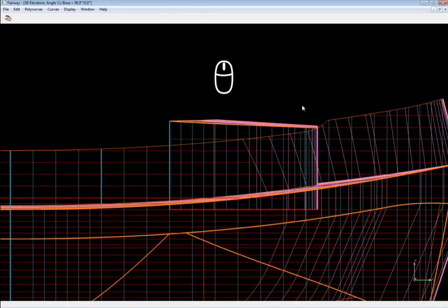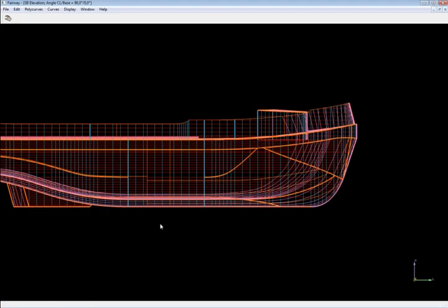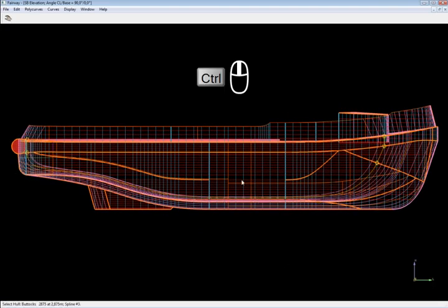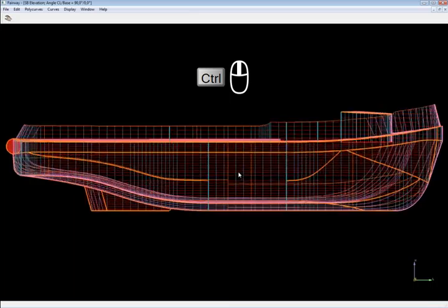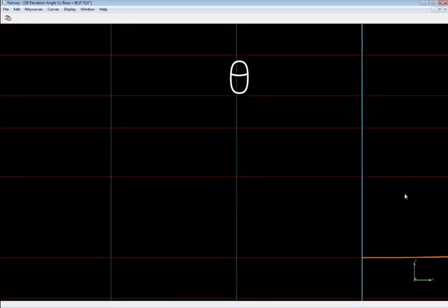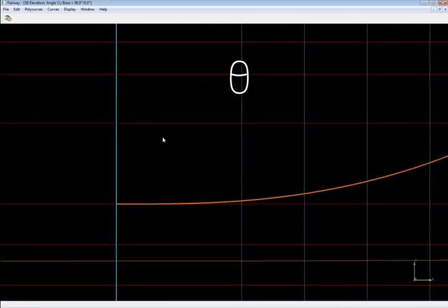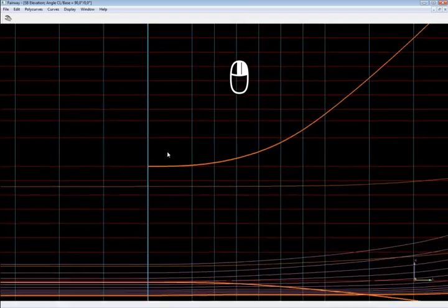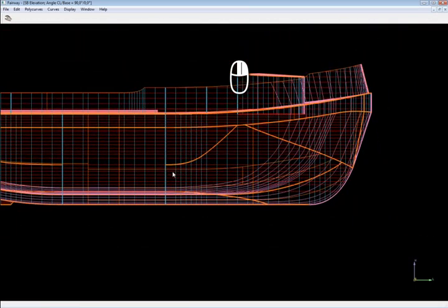Zooming with the mouse wheel happens in discrete steps. For smooth zooms, you may use the control key in combination with the middle mouse button. If you can't use the keyboard and mouse at the same time because you are holding a phone or something, you may press and hold the middle mouse button, then press and hold the right mouse button in addition to obtain the same functionality.